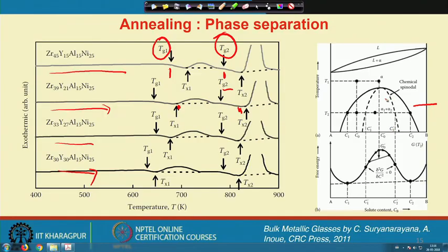In a solid solution, here there is a spinodal, and if you look at the free energy curve, and here is the average composition, there is always a chance of a decrease of the free energy, and we can get two different regions with two different compositions. Okay. And this is an automatic process by which we can go to the two different compositions.